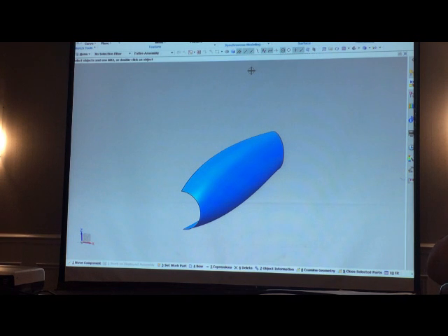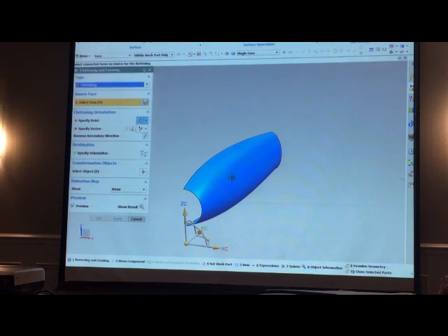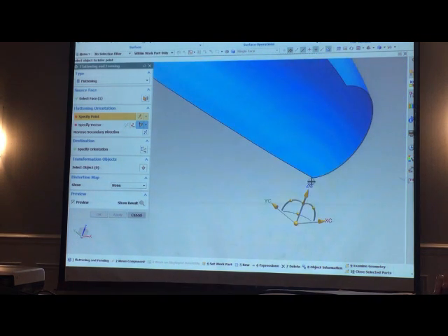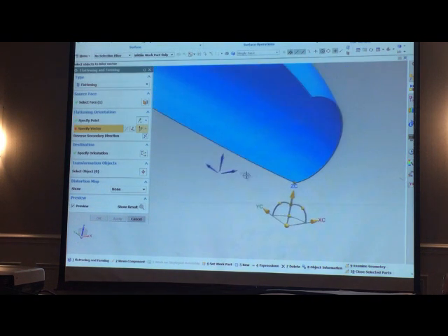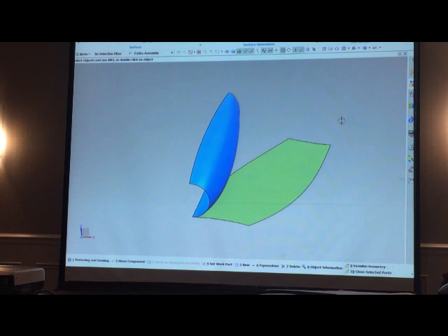So I can't put the holes in here. I've got to put it in a flat piece. So I have to flatten this first. So let's get it flat. So I go out here, and we have a new flattening routine. So I go flat, and I have to define a point for reference. Okay, I'm going to pick that corner right there, and we'll just go there. And so there's the flat of that.